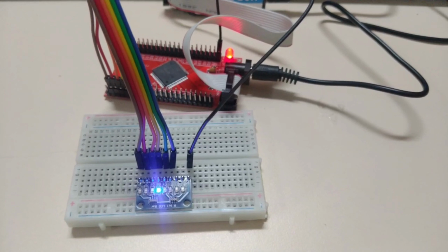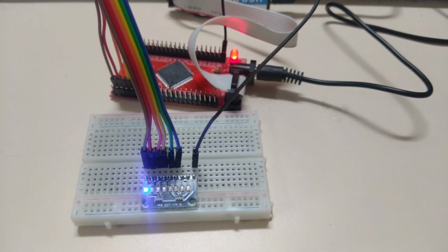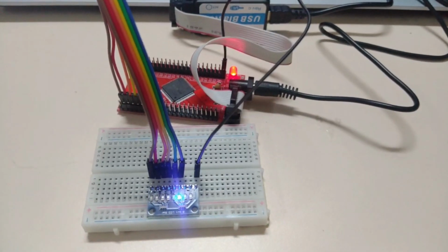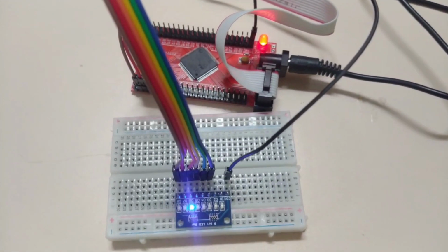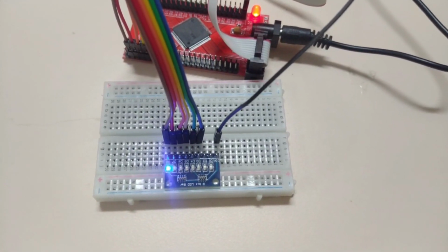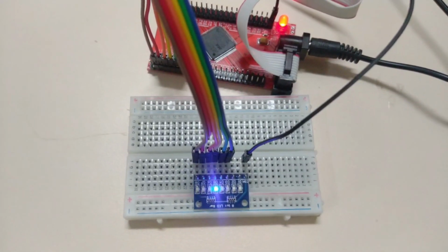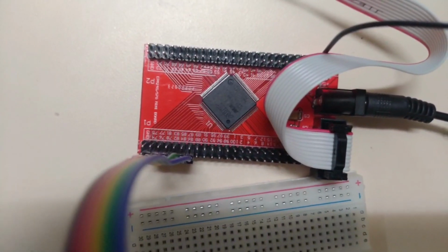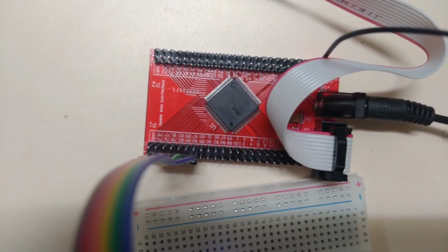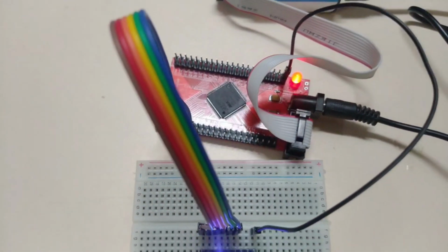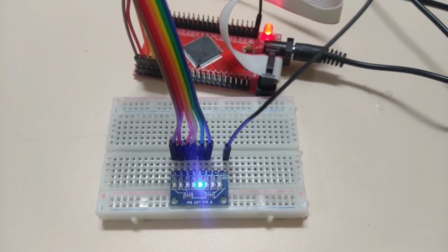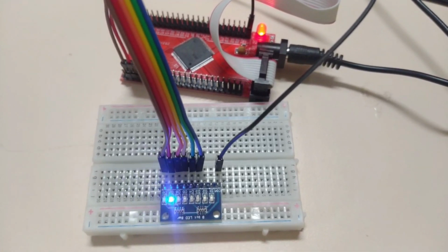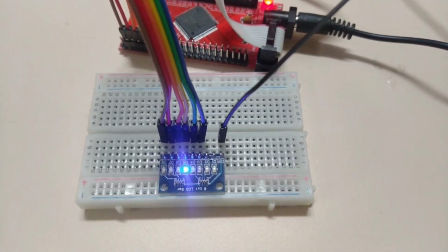Okay, this is the hardware simulation for Milestone 2. As you can see, the USB blaster and USB drive for power supply have been connected to the CPLD. The LEDs have also been connected to each pin that has been assigned for nodes A until F, which are pins 74, 76, 78, 82, 84 and 86. Each has been connected using a male-female jumper to the LED. And the VCC has also been connected to the COM part of the LED.